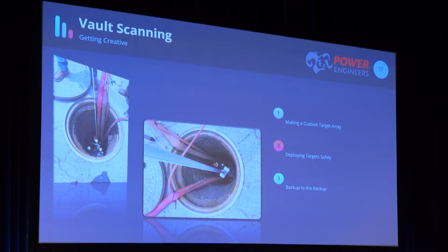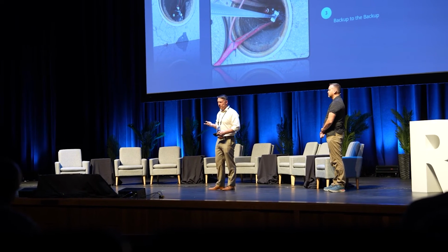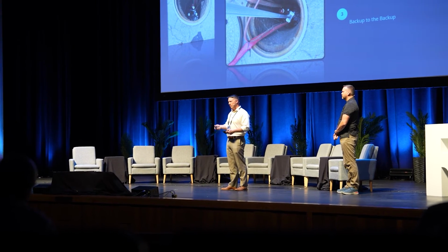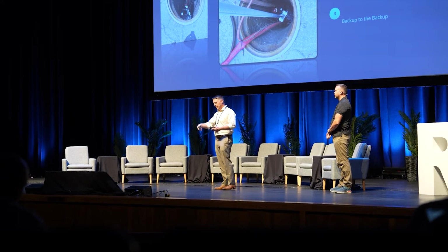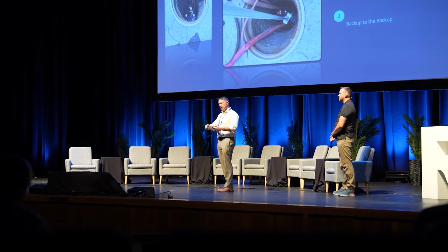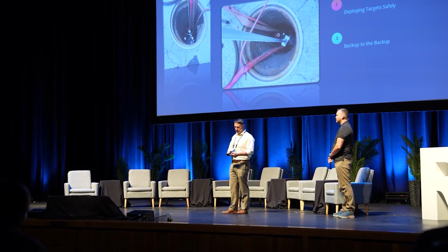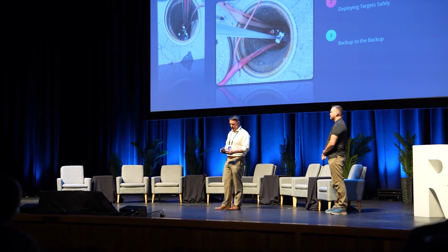A video's worth a thousand pictures. So for this project, we also utilized a FLIR One Edge Pro. It's a thermal imaging camera. We were able to lower that down into the hole and essentially just rotate it around, stop at some critical pieces, and collect temperature data on some of the hottest points inside the hole.